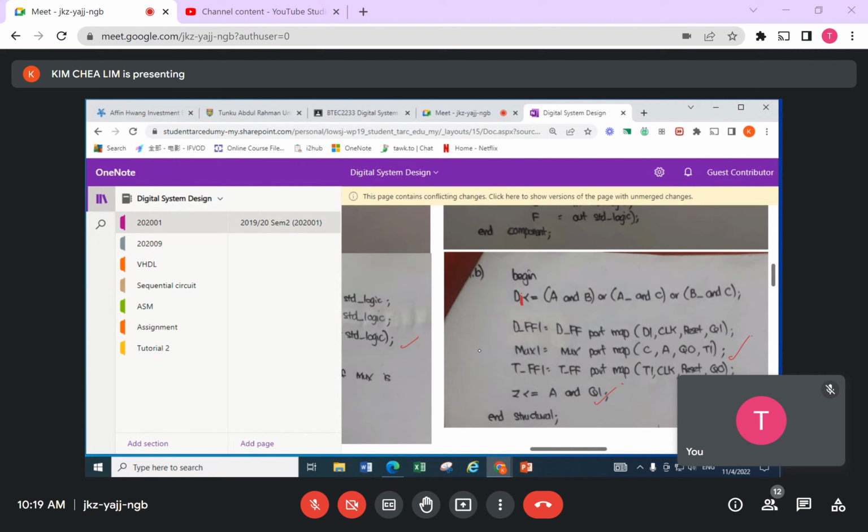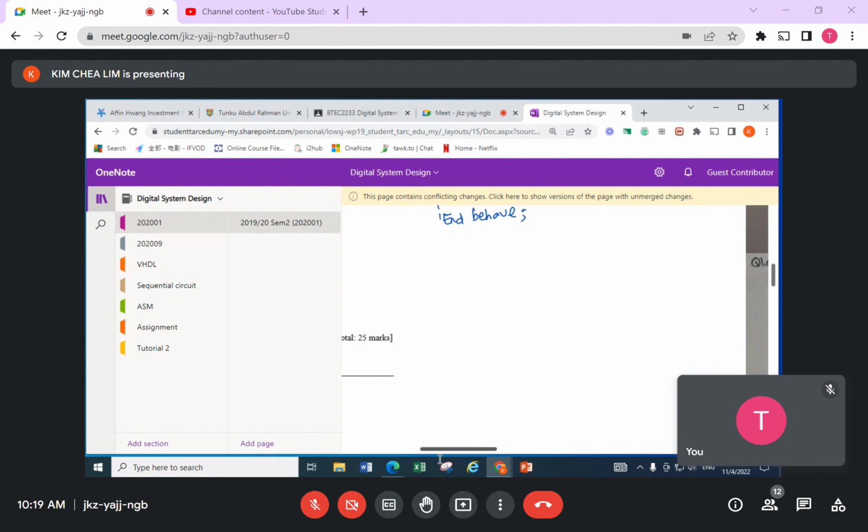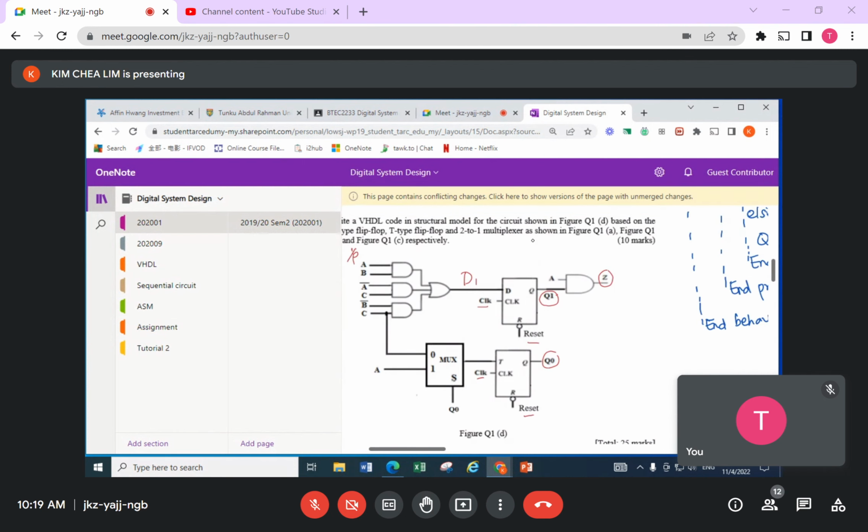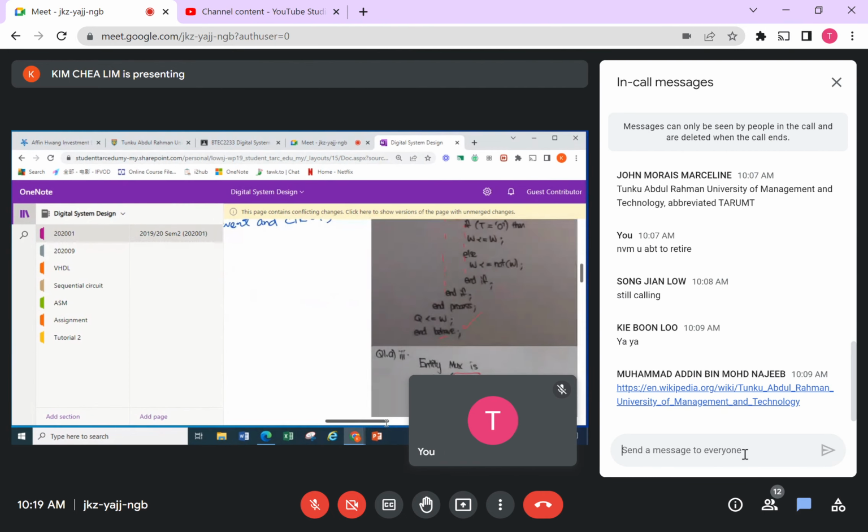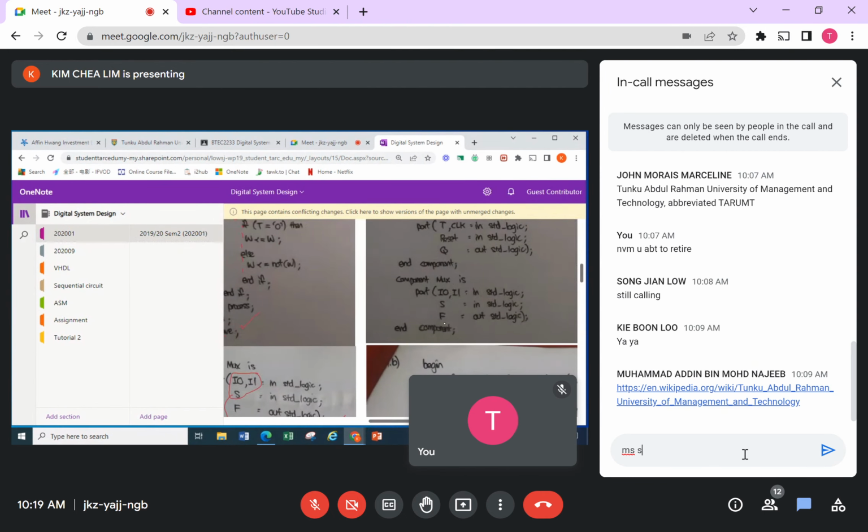Okay, D flip-flop 1 here is the first component that we are using, which is a bit difficult to keep checking this way. So we are talking about these components now, the D flip-flops. What is the connection? I need to connect D to D1, clock to clock, R to reset, and the output is wire Q1.